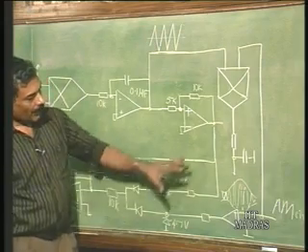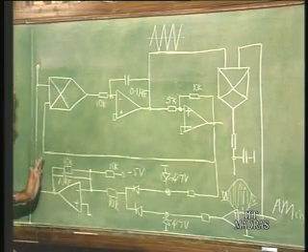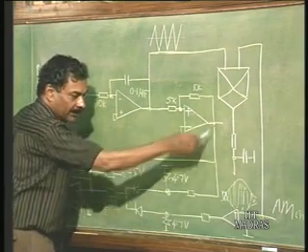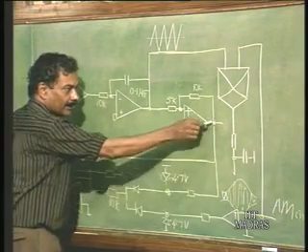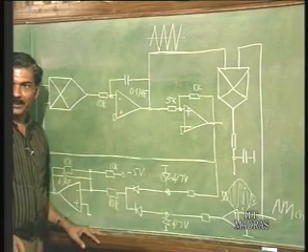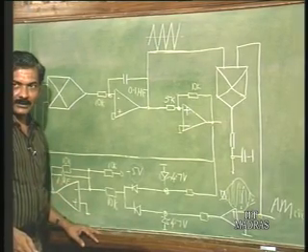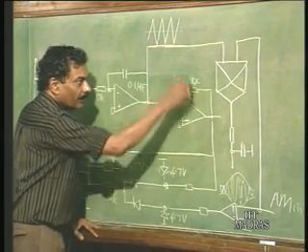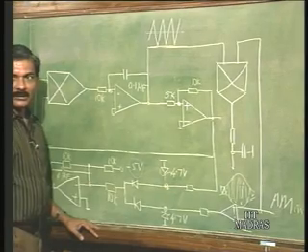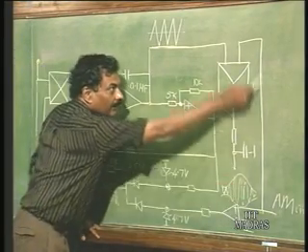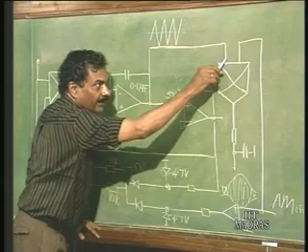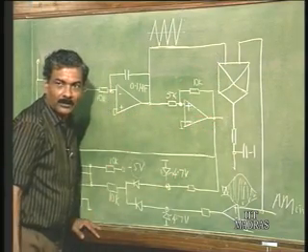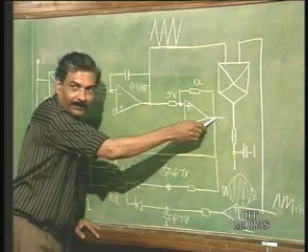Please make that correction. Therefore, this phase lock loop gets locked on to this carrier frequency, but since the phase between this and this is going to be 90 degrees if the free running frequency is the same as the carrier frequency, there will be a phase shift of 90 degrees between this and this. And if we apply this to a synchronous detector, one will be having AM coming, another has a 90 degree phase shift, this will be sin omega c, this will be cos omega c, the average will be 0. So, we have to shift this waveform by a phase shift of 90 degrees further.